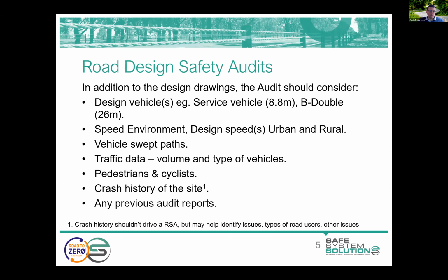You may receive some vehicle swept paths, and they should be prepared as an integral part of the design process. So if they can't readily be provided, that's a bit of a red flag. Traffic data, volume and type of different vehicles and other road users, including pedestrians and cyclists. The crash history of the site.